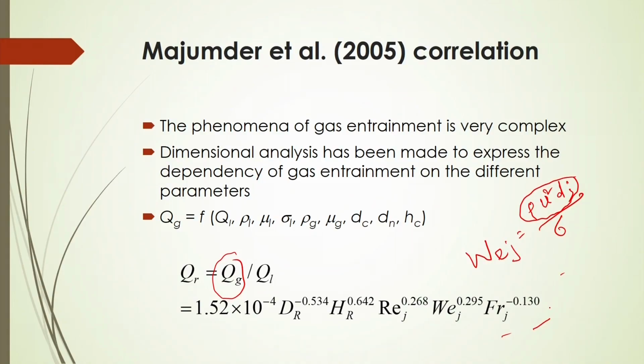So, this is one important factor, and the Froude number is also important, as to whether there is any gravity effect or not. If the liquid jet is produced from a long distance, the gravity effect will be more, whereas if it is produced near the plunging liquid position, you can have less gravity effect. That gravity effect is given by the dimensionless group, the Froude number.